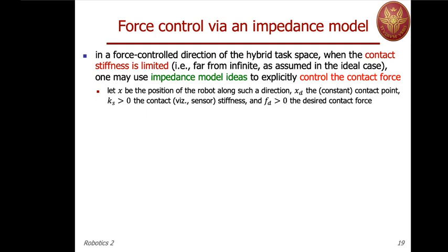Now we have seen that if we model with a spring the interaction between robot and environment, a single spring may cover essentially three cases. When the robot as a whole is stiff and the environment is compliant, or when the environment is stiff and the robot has some compliance, typically at the force torque sensor mounted on the end effector. We know that some deformation should occur within the sensor in order to be able to measure force at all, or when we have both situations, and what is in between the two springs modeling the sensor stiffness and the environment stiffness is in fact a negligible mass.